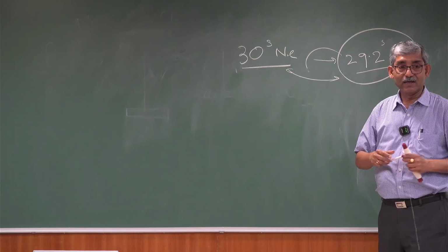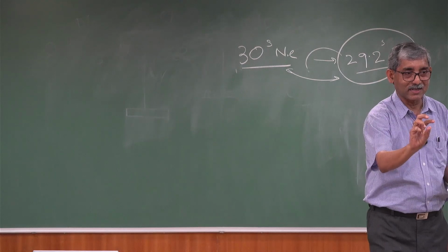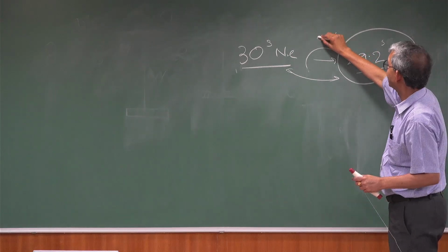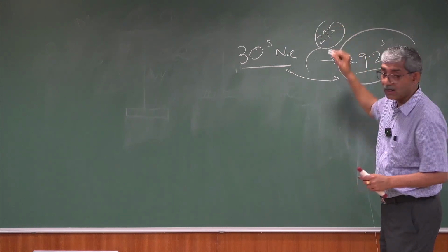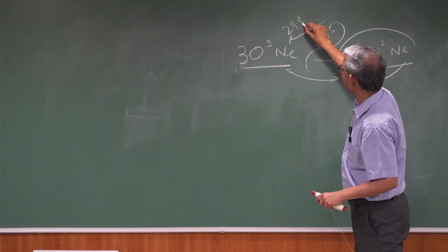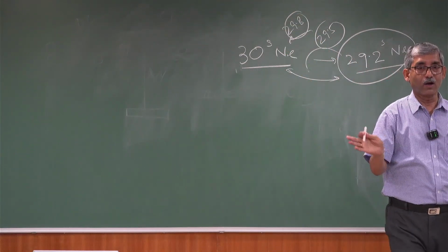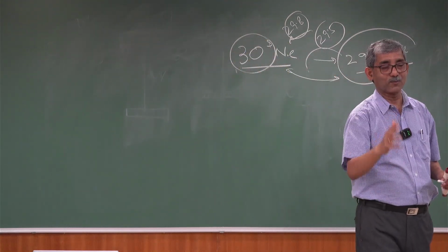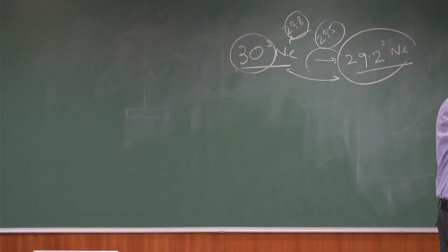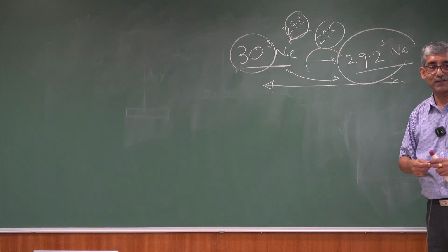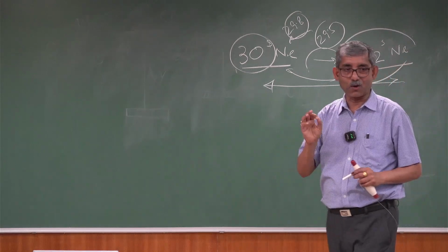Like it's very simple to stop the machine and adjust it a little bit, making it a little bit finer, and we are getting say 29.5. Again we are not satisfied, again we have stopped the machine, we are getting say 29.8. So this will go on, and reaching exactly is not possible. Once you reach, then again next time it is gone. So this will actually waste your time and your productivity. It's not a good idea to stop the machine.